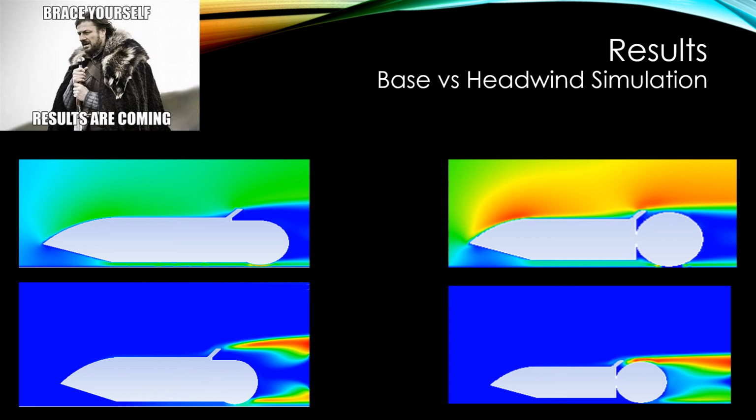That's bad. That's going to be a lot of drag because all of that air is moving slower, which means we have a big pocket trying to keep the bike from going forward. Now, if you look at the 15 meter per second velocity flow profile, we do have a slightly altered fairing design, which will help increase the flow around the bike, as well as, you notice, even though we have a higher wind velocity, we have a much smaller drag area, which is great. Shows that the design is doing its job.